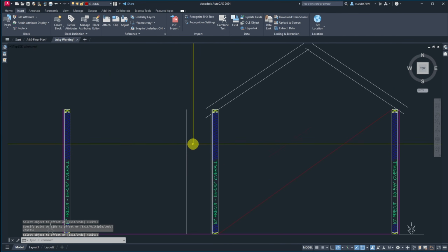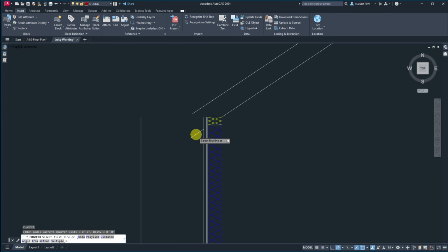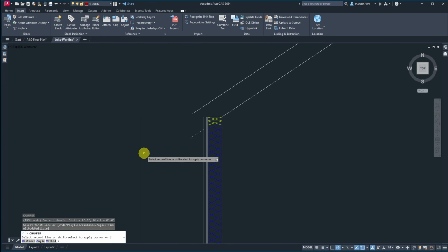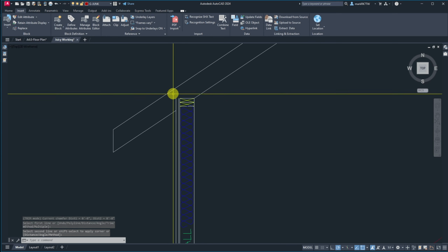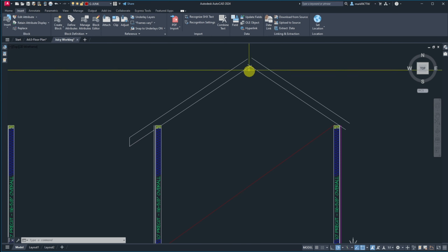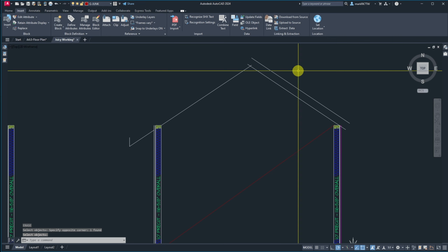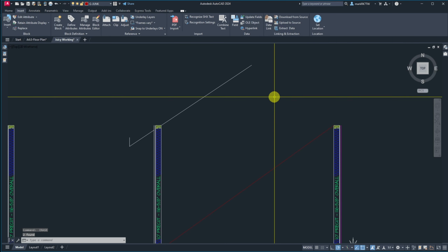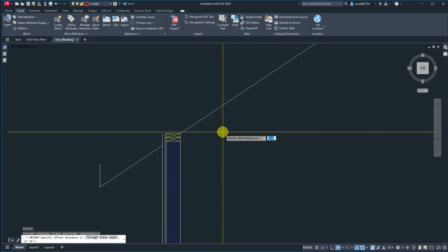And this is the existing. So I'll have to figure out how I want to show this when I get to that point. Let's get that to there, this to here. But that's quite the bird's mouth for only a 2x8. So I'm going to actually just guess that it's not. And now I'm just going to erase this too. Get one side drawn. So let's make it 2x10. 9.25.